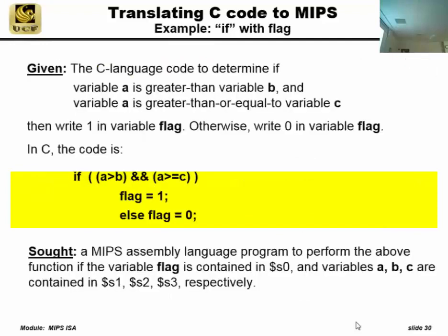This looks like we check both of these conditions, but actually, if it's an AND condition, we say AND is 0 sensitive. I put a 0 into an AND gate, doesn't matter what the other inputs are, the output's 0. So if I see here that this condition is not met, I can set the flag equal to 0 immediately without checking the other one.